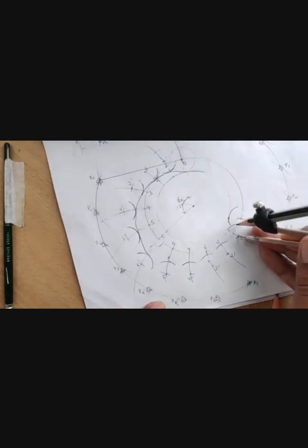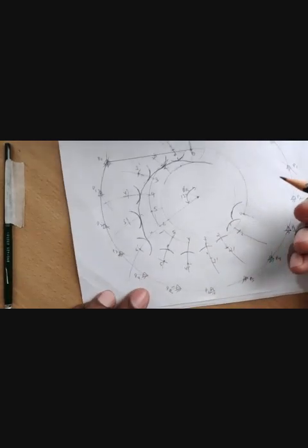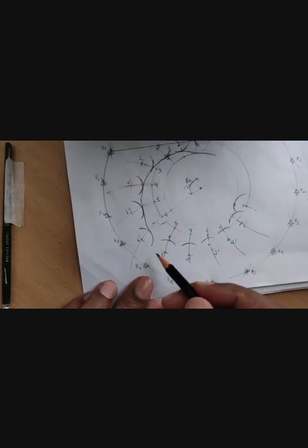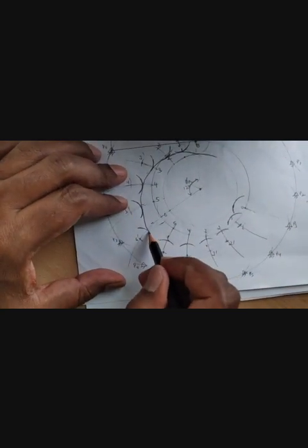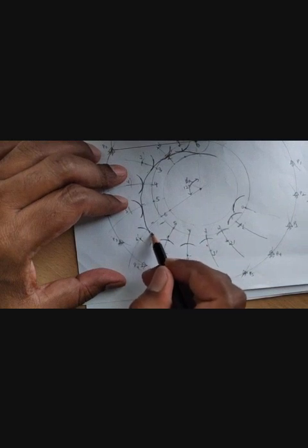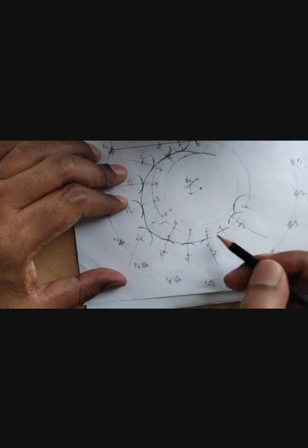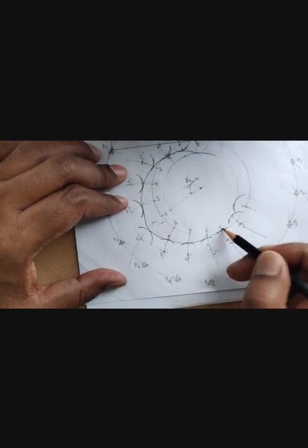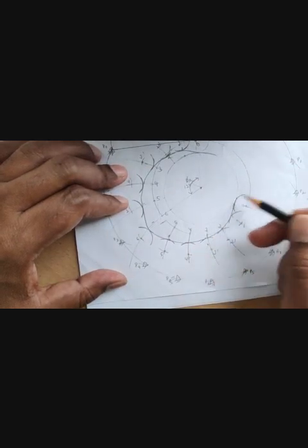So try to complete these rollers, and once these rollers are done, to lift the rollers by this height, the cam profile, the arc that you're trying to draw, should go tangentially through all these arcs of the roller, and it should go and meet the base circle.